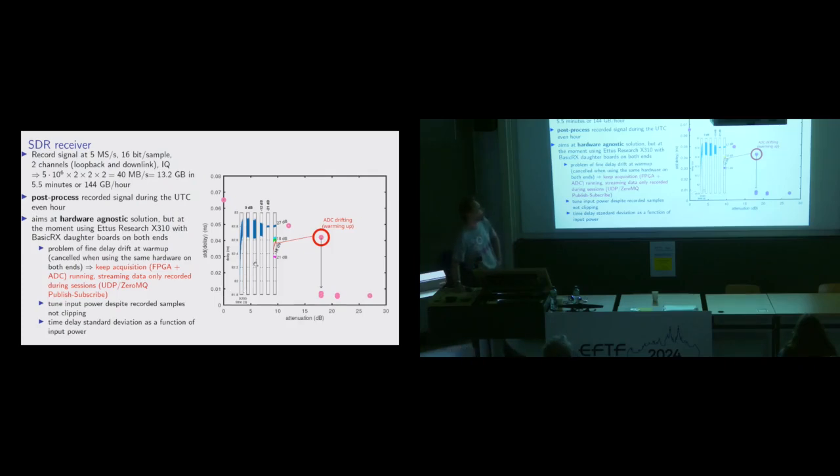And if you're not careful enough and you just wake up the SDR and don't keep it warm, you see again you have this temperature drift. Even though you attenuated the signal well enough, you still have this poor standard deviation because it's drifting at wake up. So this is your actual curve of the standard deviation as a function of power, and this is just an outlier because we did on purpose wake up the SDR and then do the data collection.